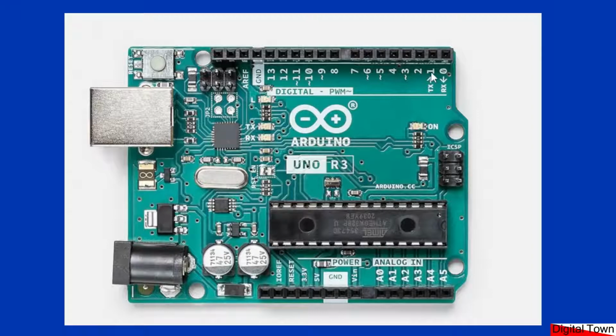So what are these pins? Well, realistically, a digital pin is a pin that can either receive digital information or send it. Now today we're going to be looking at digitalWrite, which is the method of sending data. So these pins, literally think of them as little on-off switches. Put very simply, if we turn one on, it will give 5 volts, and if we turn it off, it goes to 0 volts.